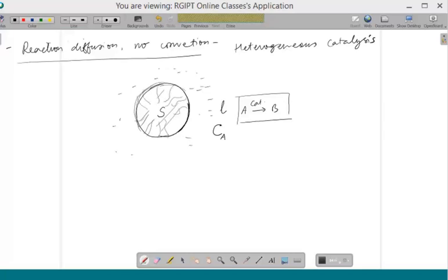Remember, this happens because of the chemistry involved in reacting A with the species which makes up the chemical makeup of the solid. So if you think of a particle like this, with A coming over and interacting only with the surface molecules of this solid catalyst particle, then you are actually missing out a lot, because all the bulk part had the potential to help in chemical transformation.